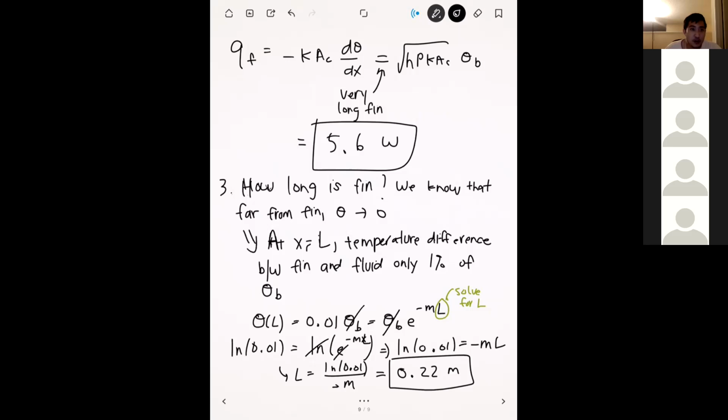And that's another reason you would do a calculation like this. If you're designing a fin for some kind of device, usually you don't want the fin to be too long because you don't have a ton of space. You can imagine riding a motorcycle and having two fins jutting out into the opposite lanes and saying to the soccer mom, sorry, it's for heat transfer. That usually doesn't fly. And so another thing you're usually interested in thermal design is, what's the length of the fin that I need to get basically the maximum amount of performance from this fin?